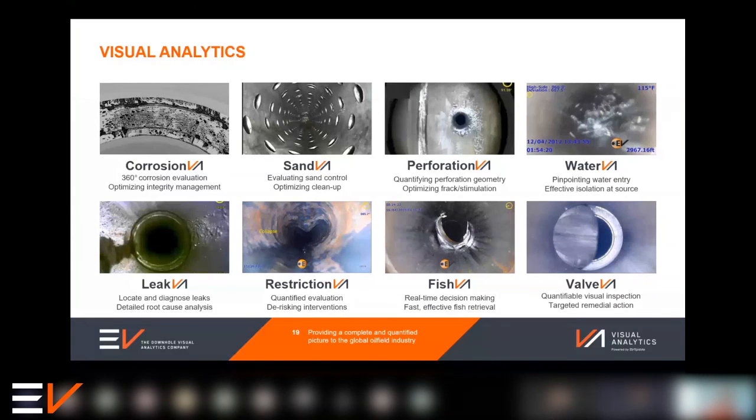Thanks, Stuart. Yeah, all of the examples that we've shown on this wall here, they're all in real time on standard electrical conductor cables. There are companies that use fiber optics, and we do as well, fiber optic enabled coiled tubing, for example. But with the video compression techniques that we use, combined with an extremely fast and stable wireline telemetry, we get very, very high quality real-time video on regular monoconductor cable. So really nothing special required.